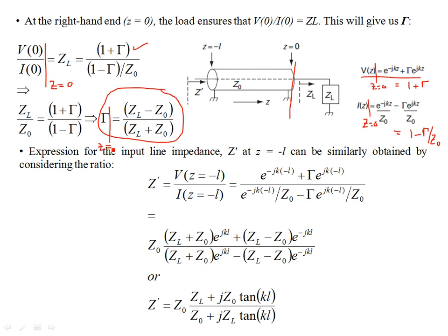Mind that the reflection coefficient is again a function of z. It's space related. We are finding this reflection coefficient at the interface, where by interface I mean the impedance of the medium changes. Over here there's Z0, and at z equal to 0 this transforms into ZL, a load impedance different from Z0. So you have reflection, and the reflection coefficient is in terms of the impedances being considered here.